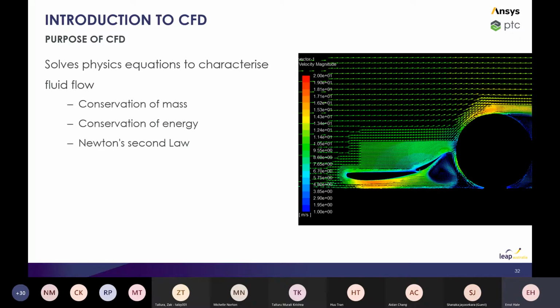So it can be used for picking up pressures, forces, density, mass and momentum in a case for an aerodynamics vehicle, so a vehicle with aerodynamic surfaces. But there's a myriad different uses for CFD, things like multi-phase, where you can have fluids and gases in the same simulation. You can have discrete phase modeling, so that means we've got particles coming in, species, we've got different types of gases and interactions. We can also have some combustion in those species simulations, loads of different applications.